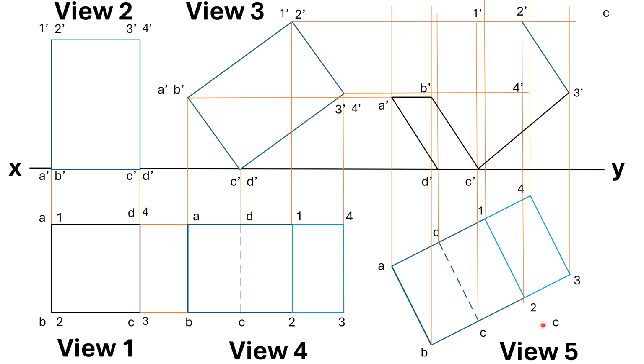And after that, you need to close all the outside lines. So let us say this is the projection of the final solid. No hidden lines appear at the outside boundary. Even though an edge is above this line, because it is the outermost edge boundary, you are able to see it in the view. So we need to close the outside lines.